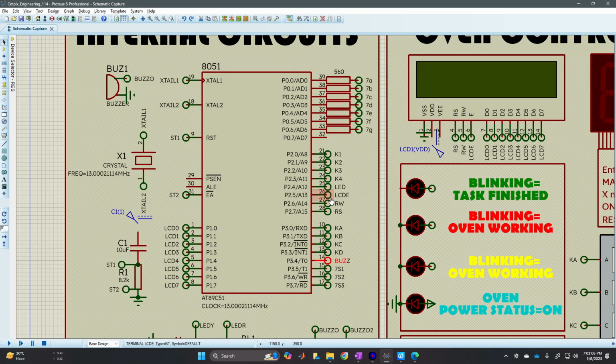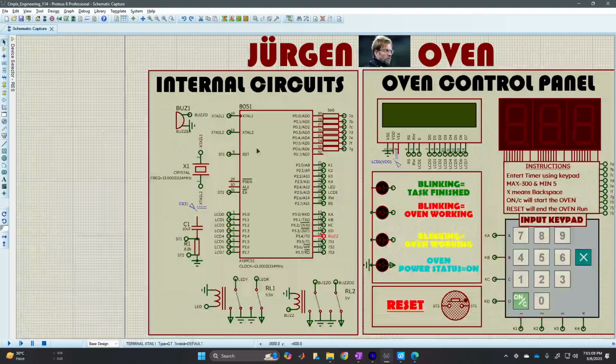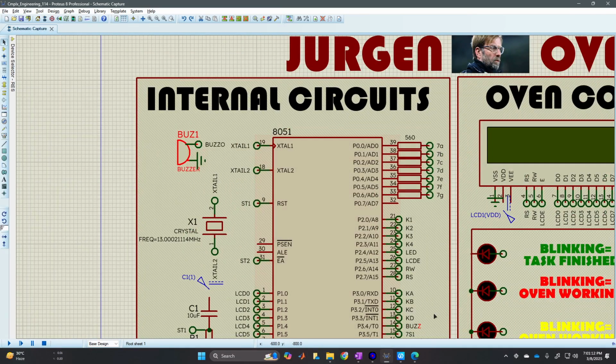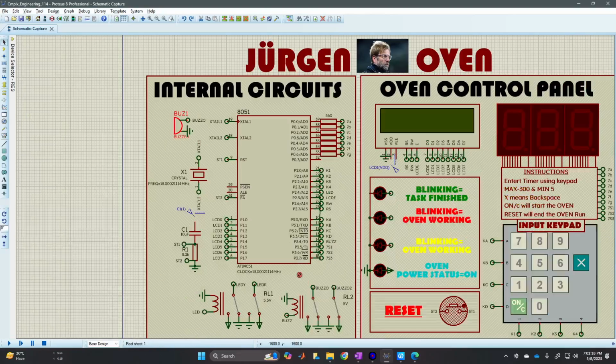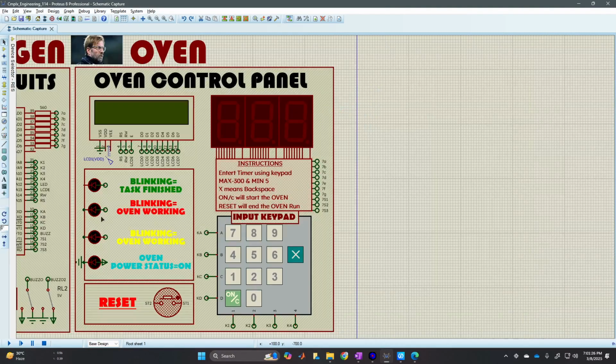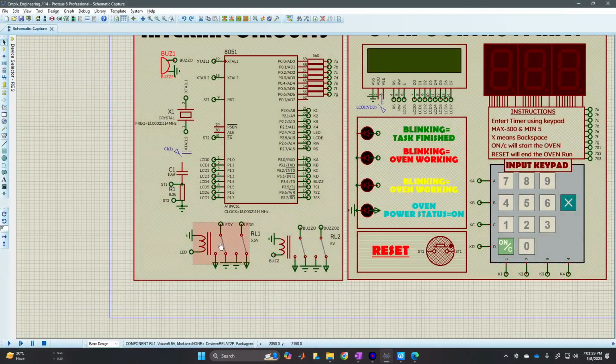So what I have done, I connected the buzzer with 1 pin and the LED with another pin. But sorry, I need to operate 2 LEDs here, a red one and a yellow one, and they need to be flashing. So I used a toggling relay, where the red and yellow ones are connected in alternate polarity, so that they will not blink together. If the red one is on, the yellow one will be off, and vice versa.